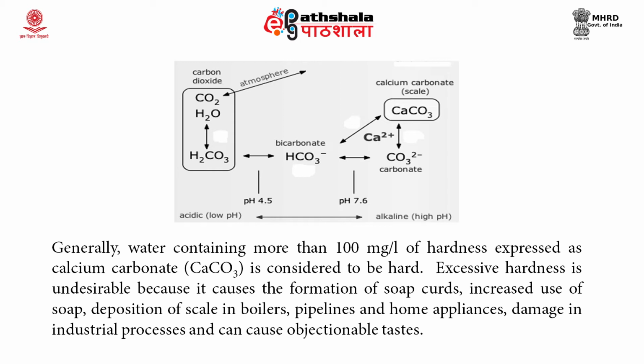Generally, water containing more than 100 mg per liter of hardness, which is usually expressed as calcium carbonate equivalent, is considered to be hard. The excessive hardness is undesirable because it causes the formation of soap curd, increases the use of soap, and causes deposition of scale in the boilers, pipelines and home appliances. It also damages industrial processes and can cause objectionable taste in the water.